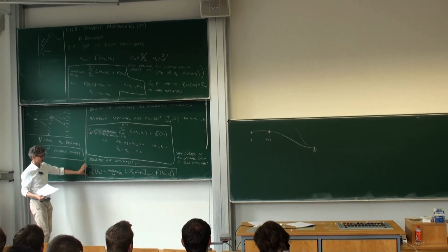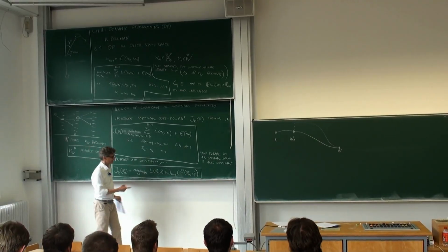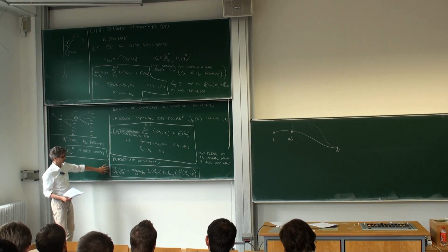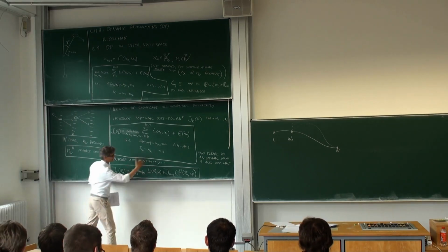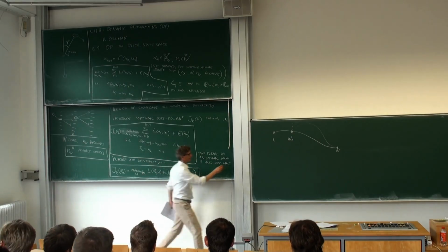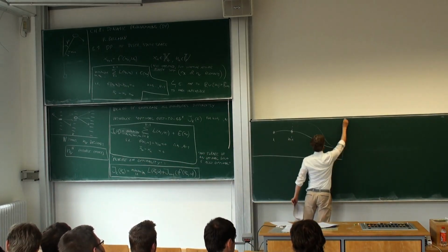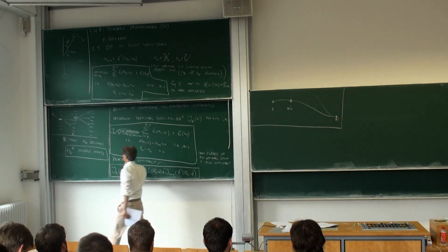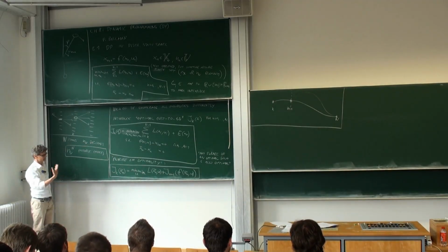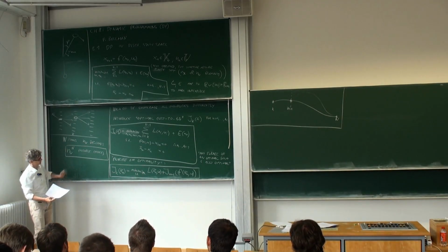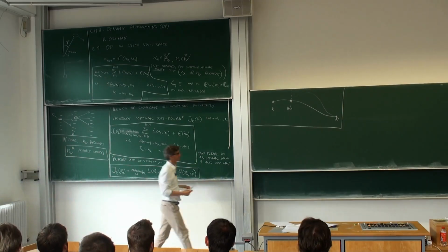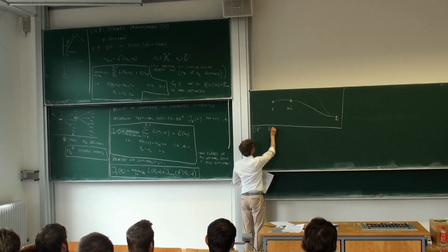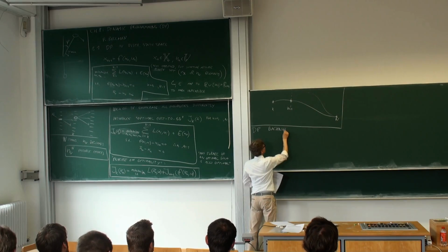And this is culminating in this equation, and that is a recursion. We can interpret it as a recursion, because now what we could do, and that's the dynamic programming algorithm, is start at the end and then compute this cost to go step by step. Then we know more about the dynamics and the optimality, and we can use it to make our decisions, and we will see that it's more efficient. So we have the DP, a backwards recursion. That's the first part.